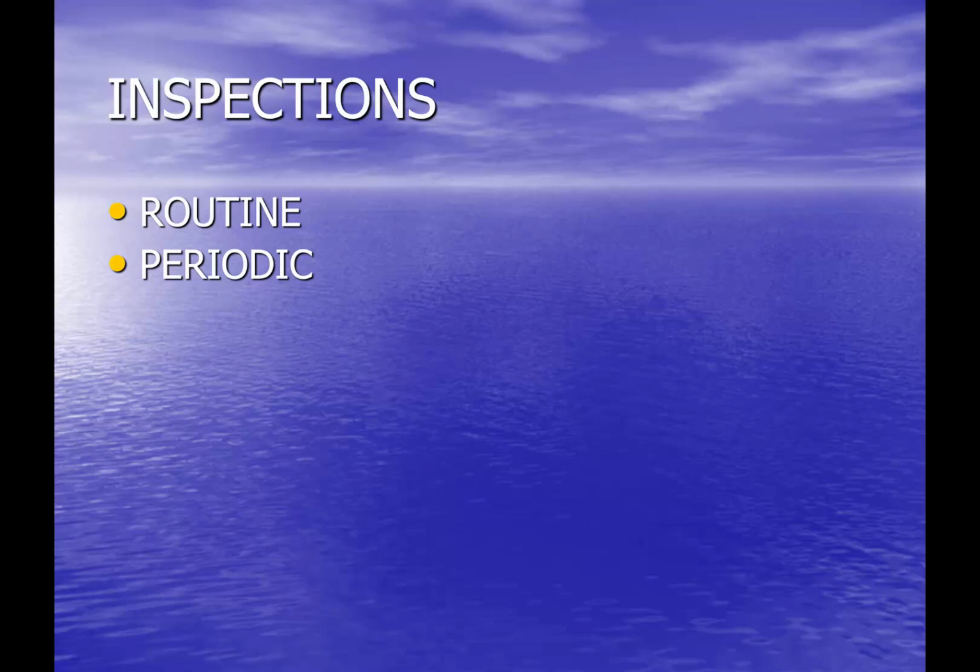Now this is one where you are going to see things you can't see from the ground. You get on top of the tank, you're going to look at the roof hatch, you're going to look at the vents. Again, you're going to verify security, especially of your roof access, your hatches and your vents, to make sure nothing bad is going on with any kind of malicious access to the reservoir. So again, we, El Toro Water District, are going to do this more often than quarterly, but just understand the different levels of what these inspections would entail.